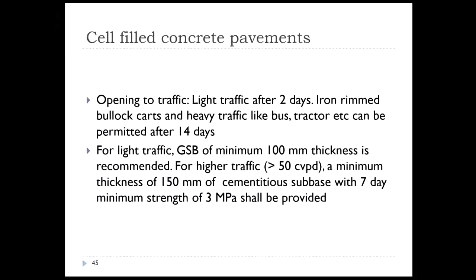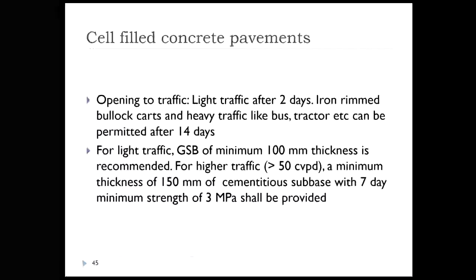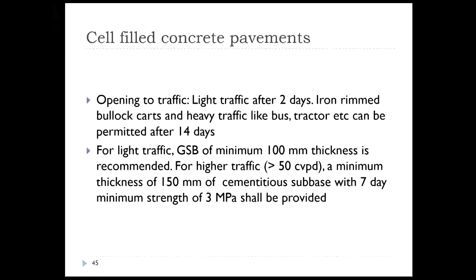And for higher design traffic, we can actually go for cementitious layers. Basically, this is similar to your interlocking block pavements, where the success of any of these block pavements is basically how well you compact your lower layers. Your lower layers should be sufficiently and adequately compacted.